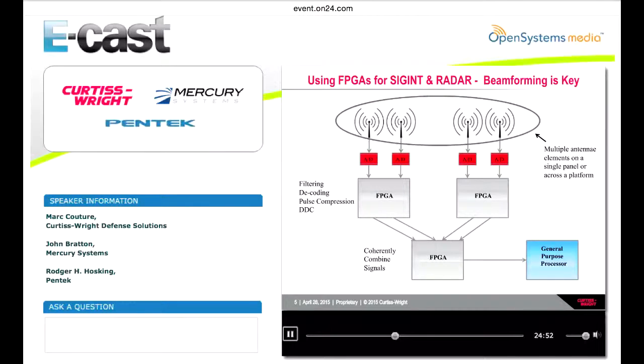So this is where, for instance, you're conducting beamforming, or say in a SIGINT EW app, like a time difference of arrival, where if you want a very fine circular error probable, if you're trying to stare at something that's 20 kilometers out and you want to know within a very reasonable amount of certainty where that thing is, you want those ADC converters synchronized down to the sample clock, in fact, down to the rising edge of the sample clock.